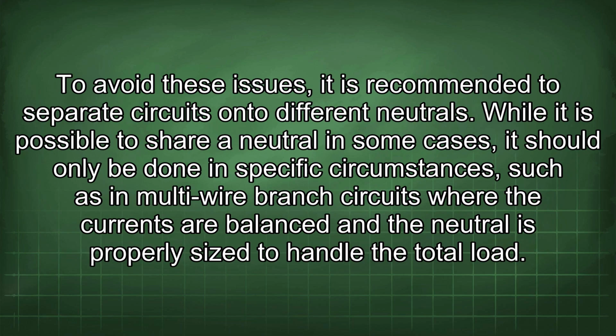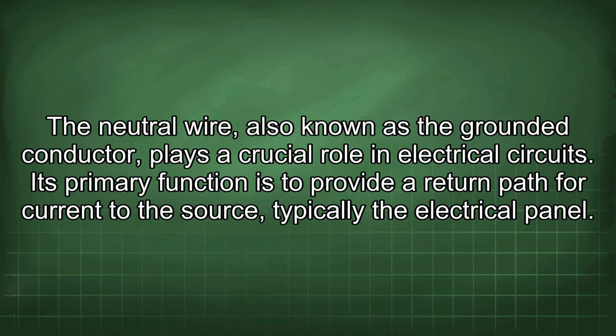To avoid these issues, it is recommended to separate circuits onto different neutrals. While it is possible to share a neutral in some cases, it should only be done in specific circumstances, such as in multi-wire branch circuits where the currents are balanced and the neutral is properly sized to handle the total load. The neutral wire, also known as the grounded conductor, plays a crucial role in electrical circuits.